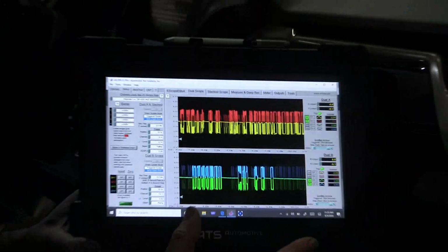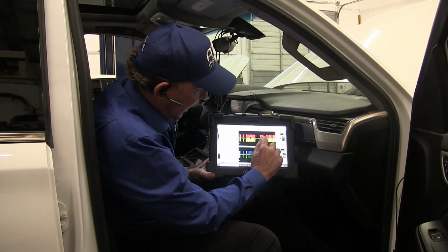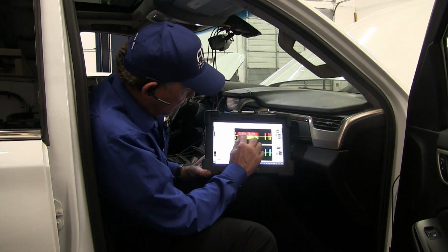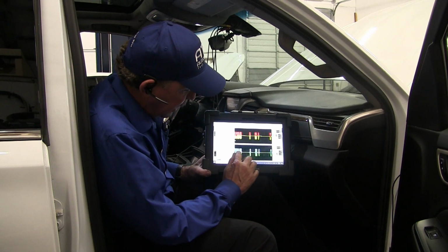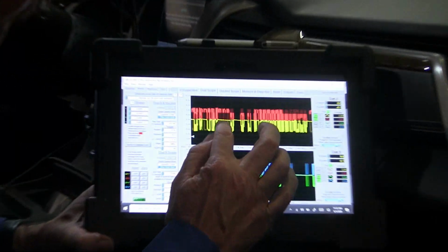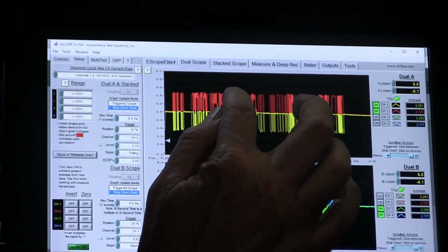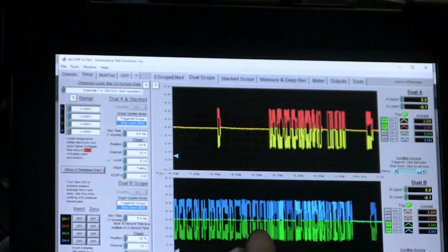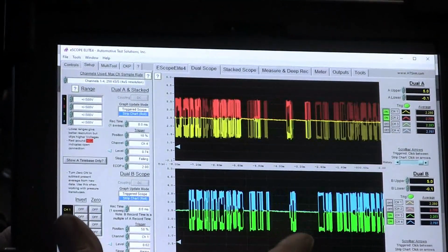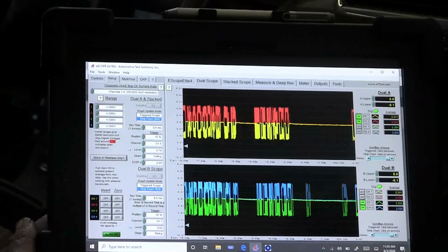What we're looking for now is the bias. This is the non-recessive bit. That's the 2.5 volts, or the active mode, and what I'm looking for is for it to pull the bottom of it to pull into the top, the high line, or the high line to pull down, or something to happen on the data. So we want to watch this and see what's going to happen.